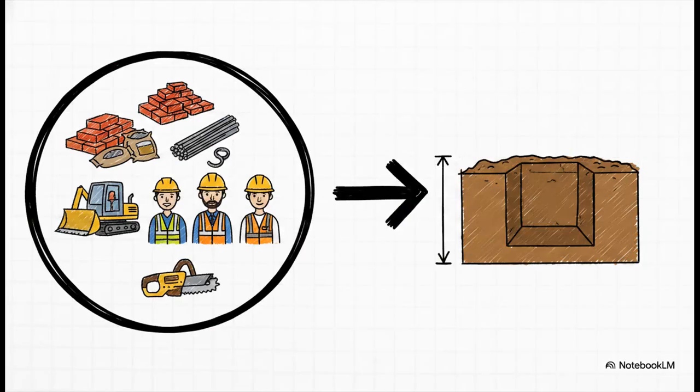Okay, now we bring it all together to find the final unit cost. This is the true cost per meter to lay this mat foundation. We take our material cost of $3,913, add that massive labor cost of $23,228, and finally add in physical resources, say $1,000 to hire an excavator and some cutting saws for the week.